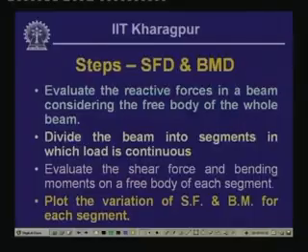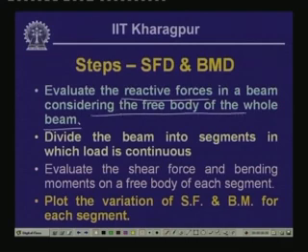Now, if you have such a system and if we are interested to draw the shear force and the bending moment diagram, then how do you go about it? What are the different steps? The first thing, as you have noticed, is that we draw the free body diagram of the whole beam, and thereby we represent the supports with the reactive forces, and we evaluate those reactive forces based on the equations of equilibrium. So, the first step will be to evaluate the reactive forces considering the free body of the whole beam. Then you will have to divide the beam into segments in which load is continuous.